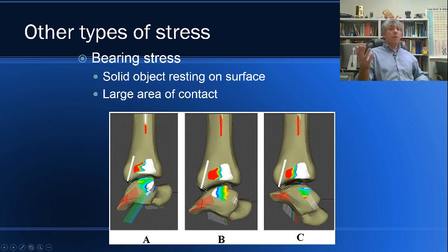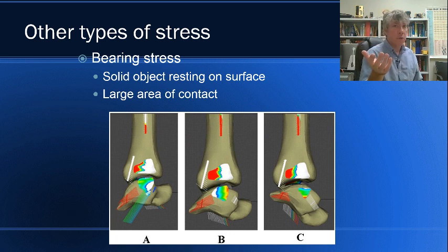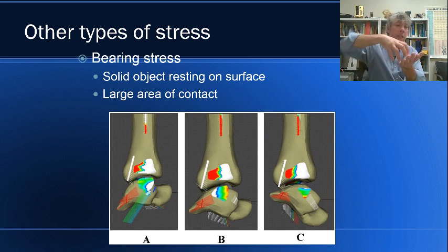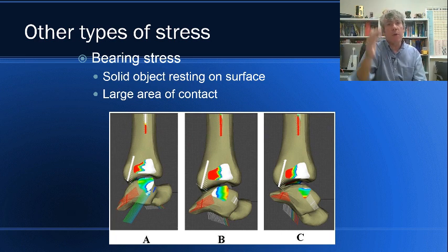Think of a ball bearing, for example, where there's a spherical ball, a spherical rolling element, and theoretically the contact is simply a single point. But in reality, since no material can resist infinite stress, and remember stress is force per area, and if the area is zero, well, that's infinite stress, the ball literally has to flatten out some. Imagine a beach ball sitting on it, or an exercise ball, and how the bottom of it must flatten out somewhat to have a contact patch to support the bulk load.